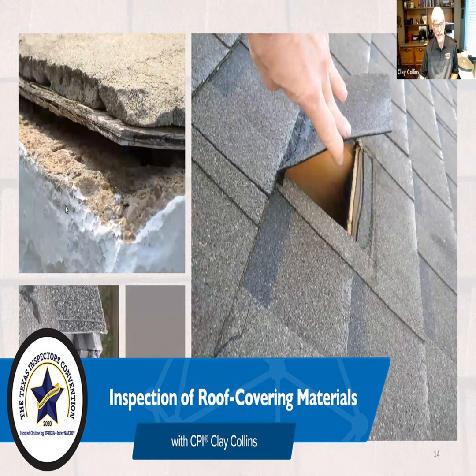Now, the fasteners apply to all roof covering types, but the majority of them are going to apply only to, well, I guess that's wrong. It's going to apply to all, but we're just talking about the asphalt. We can't see those. Now, when I do windstorm inspections, I actually have to go in and lift up the shingles to count the nails.